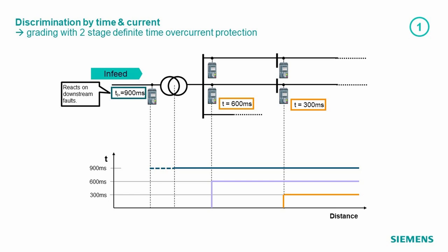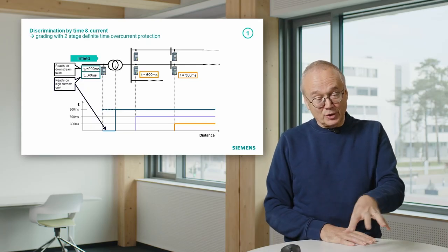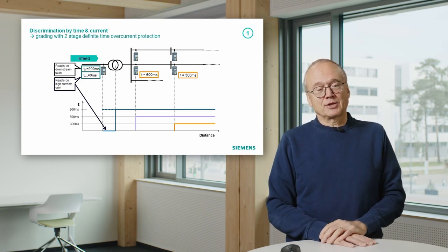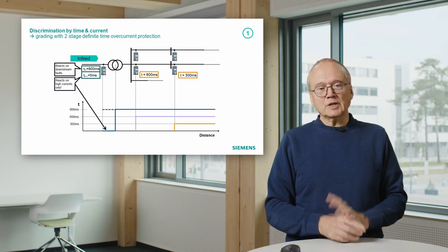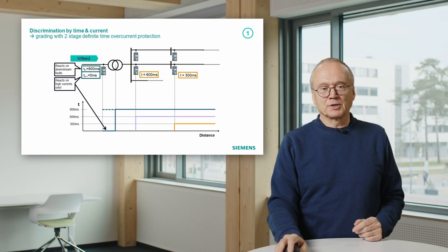It must be a short circuit on the high voltage side, and there is no need for a long time delay, and then it can trip faults on the high voltage side of a transformer without time delay. That means we must do short circuit calculations for the system and then make the timer setting in an adjusted way. That is a thing what you often find in connection with transformers.